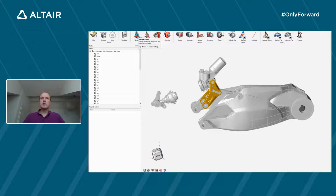So the ground part is basically the fixed part in the simulation, and the other parts being then, for example, rigid or flexible parts, which are allowed to move either as a rigid group, so basically meaning with different parts grouped together as a solid or rigid entity, and other parts could be defined then as flexible, meaning they can deform during the analysis.